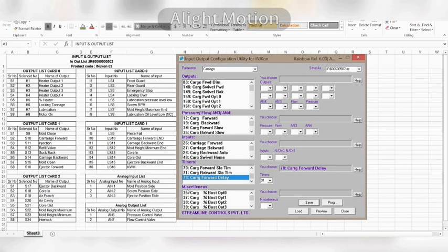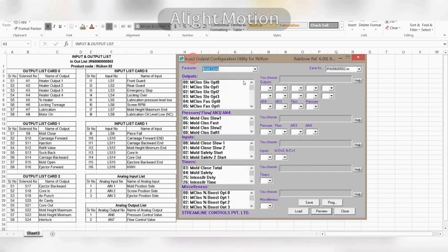Our fifth step is miscellaneous. Here in the miscellaneous function, if you want to define any interlocking function or linear scale, you can program according to our wiring list. There are 3 analog inputs. In the first channel, mold position side; in the second channel, screw position side; and in the third channel, ejector position side. Now if we want to define the linear scale of the mold, in parameter, in mold close, we will go into the miscellaneous. We will search for mold side analog channel number, and select the channel by 01. Tonnage side has no linear scale, so we will keep 00 disable.